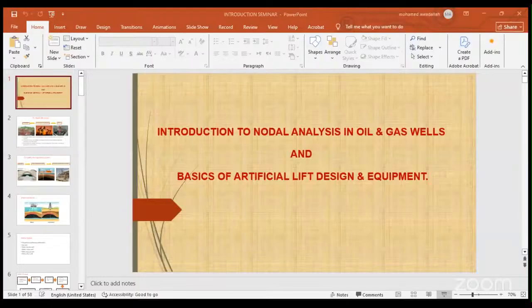Then, once we confirm there is a presence of hydrocarbon, either oil or gas, we start to develop this concession or field, which is the second stage of any field, by drilling more wells near the first wells and developing production from this concession. By drilling more and more wells, we evaluate this reservoir, estimate the volume, and perform testing, build-up tests, and reservoir limit tests to see how much volume we have inside this field. We then decide the field development plan, or how many wells we will drill and produce.